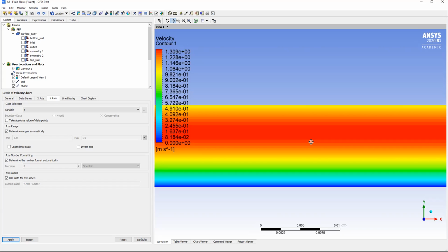But it's not quite like a Couette flow, because there isn't that boundary layer on the top here that's creating that same nozzle effect. There's the one on the bottom, and sure, it's kind of creating a nozzle, but it's not happening at the top. So in essence, the velocity increases, has its maximum here, and then tapers off to match the velocity of the top plate again.